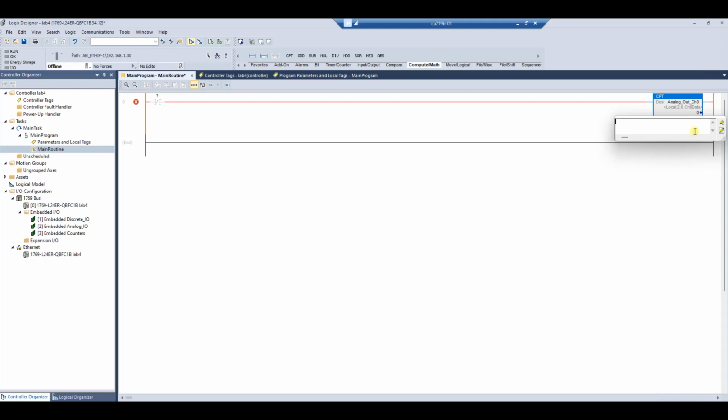So I type in, well, let's actually type 4,500, which is going to be 4.5 volts. Okay, and I want to do it whenever push button 0 is pressed, and push button 0 is normally open. So when it's not pressed, this should be true. And I'm doing this because I'm setting up this program remotely. So I'm going to type in PB0.